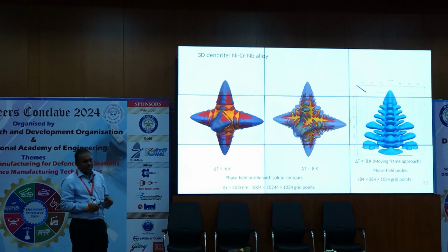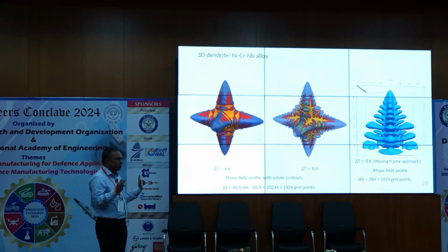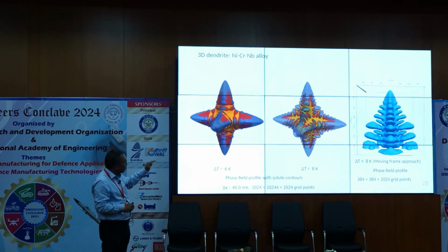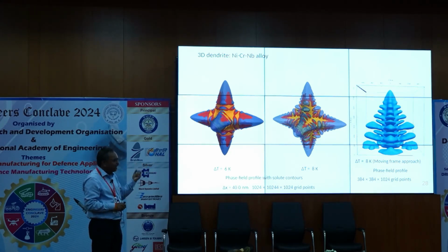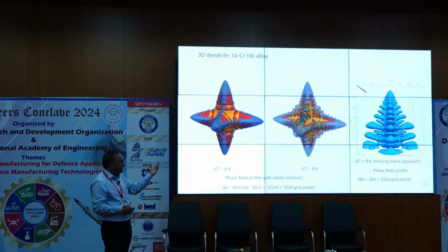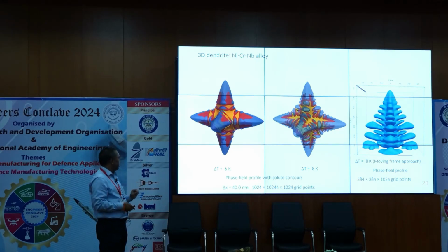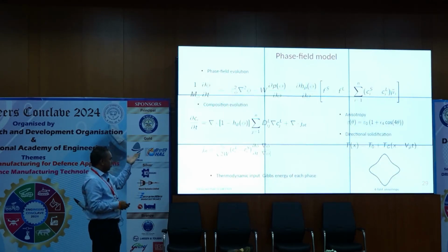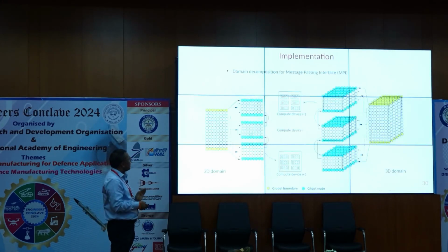We can do such fantastic three-dimensional simulations of complicated multi-component alloys, showing the contours of different compositions, showing you where the segregations are, taking into account Gibbs-Thomson effects, kinetic effects, etc., and telling you why the nickel compound will form at certain locations and why not, etc. And these can be solved thanks to the phase field models.